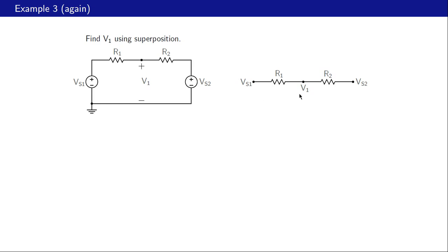What we will do is take Vs1 first, take Vs2 as 0, and what is the meaning of Vs2 equal to 0? That means this node voltage would be the same as the voltage at the reference node or the ground node. That means it is 0 volts, and that is shown using the ground symbol like that. And now in this case V1 is given by voltage division.